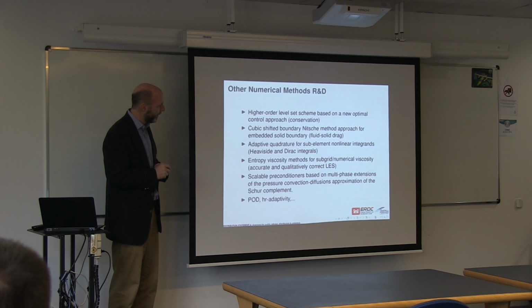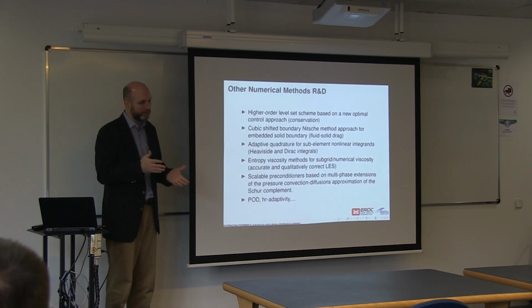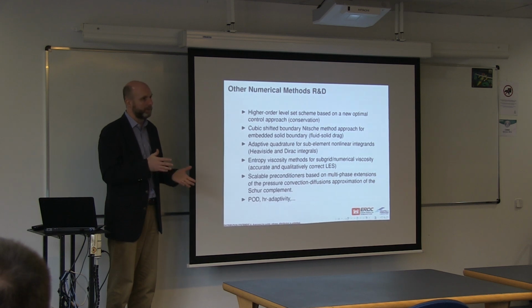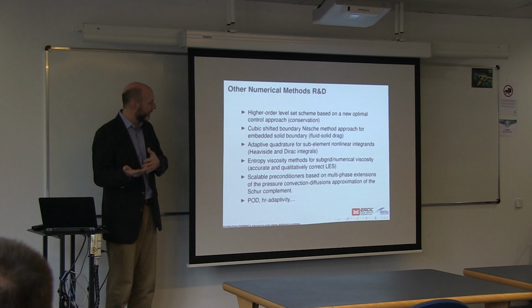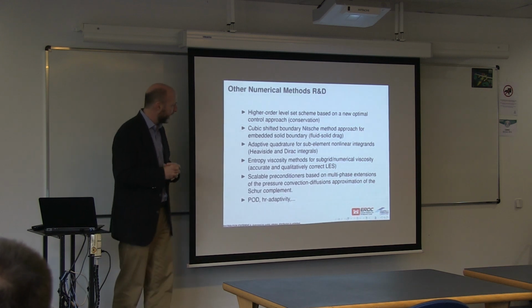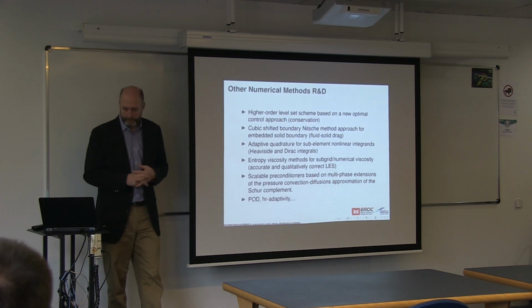We've also been in the process of shifting our stabilization schemes in Navier-Stokes equations from variational multi-scale methods or SUPG methods to entropy-viscosity type stabilization schemes. And we're also working on scalable preconditioning.